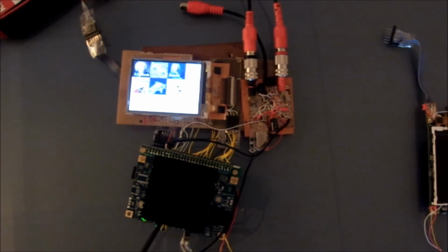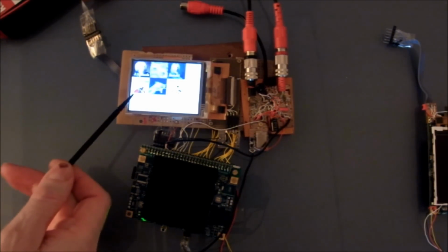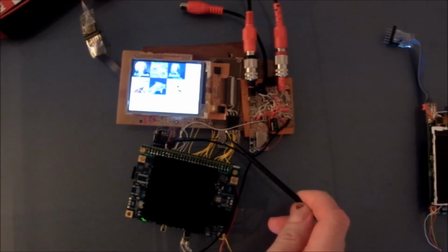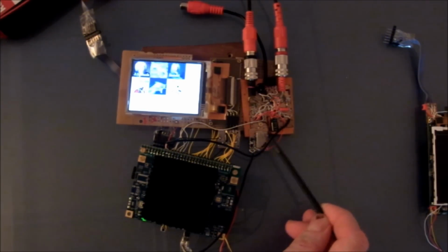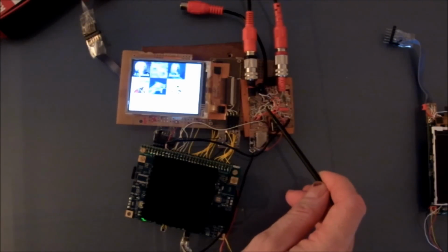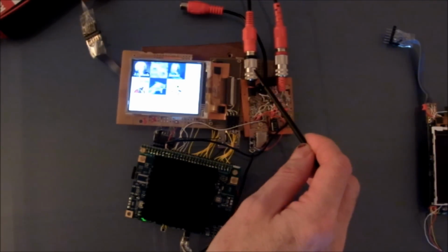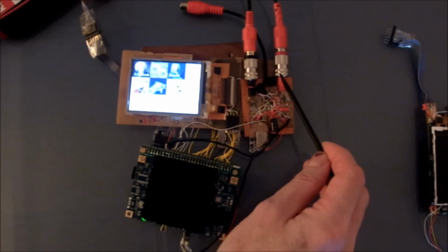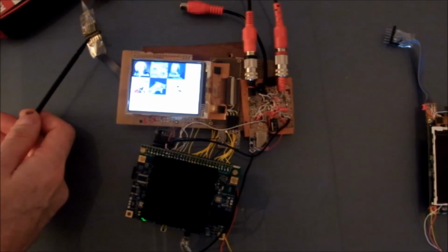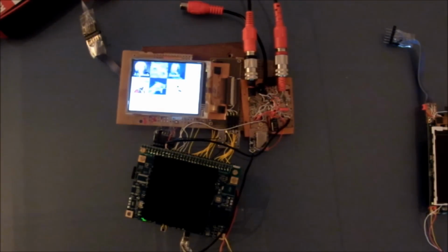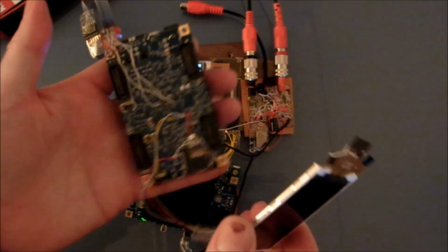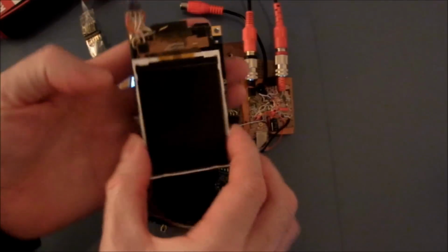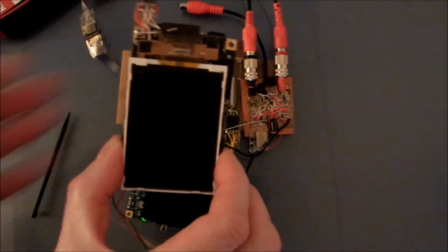So the parallel TFT display, resistor divider for the touch panel, SPDIF time base, voltage translator for SPDIF, low pass, high pass SPDIF outputs, JTAG connector, and a serial port to NetMF Visual Studio. I intend to make a PCB with a TFT, so nice footprint.